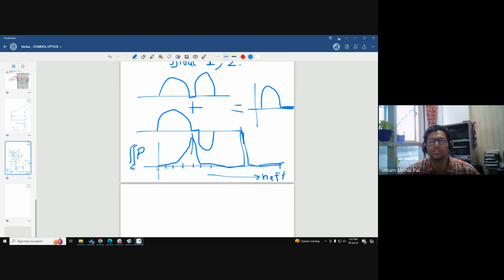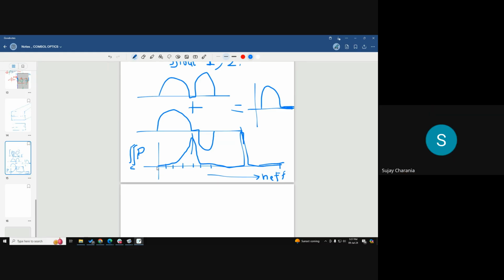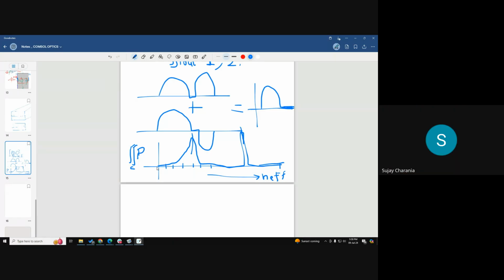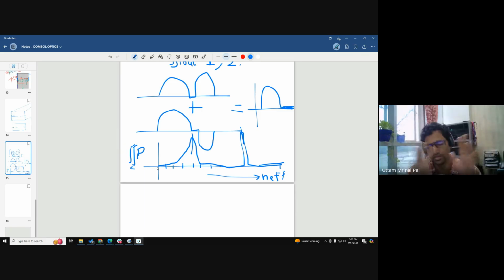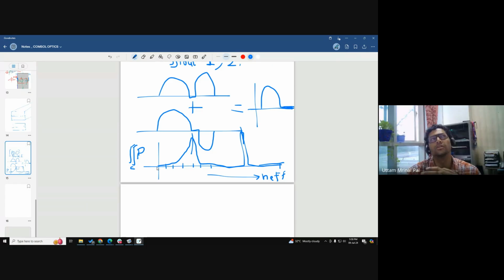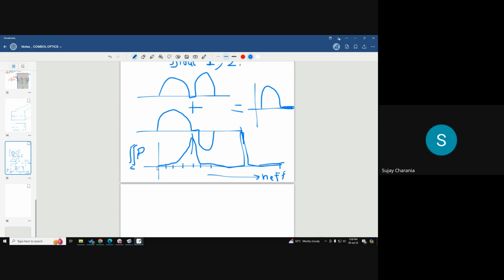Yeah, I mean, you're talking about mode conversions that happen. Because when we launch the fundamental mode, and if we tell COMSOL to find 10 other modes, or 1,000, then integrating is the overlap of all the modes that exist through that propagation. How can you differentiate? Because eventually it's just the electric field at each node point, so to differentiate between these two is very difficult. So finding one particular mode power would be a little bit tricky, right? It won't be just integrating.